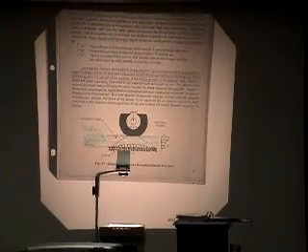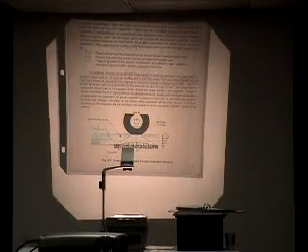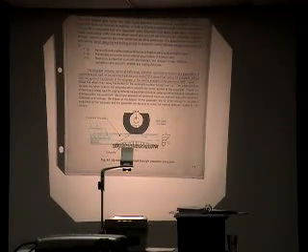I think if it spreads out, the stress is going to be less, so the subgrade will be able to carry it. And if you just think about it, the stresses in this pavement structure are the very greatest in the surface layers. So those layers actually have to be stronger than the lower layers, because the stresses are going to be great. And I think you can also see that the thicker that pavement is, the more it's going to spread the load, and therefore the pavement will be able to carry more load.